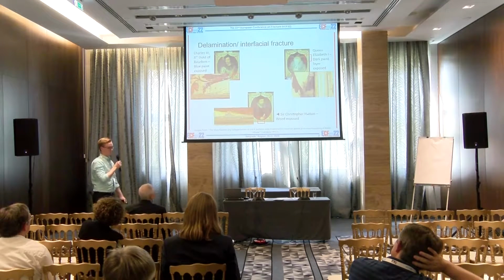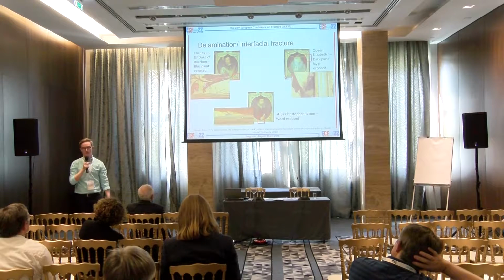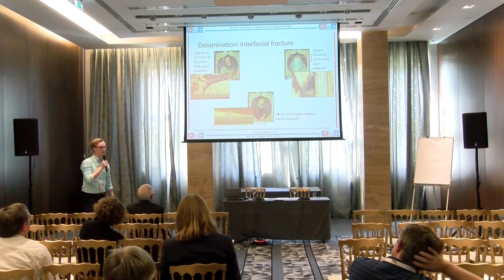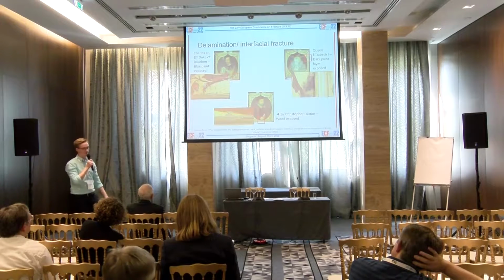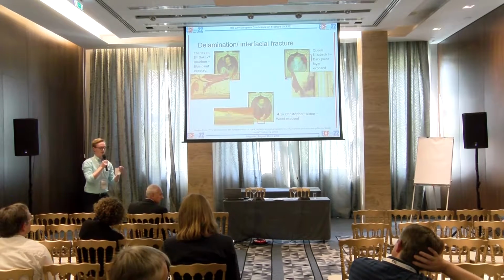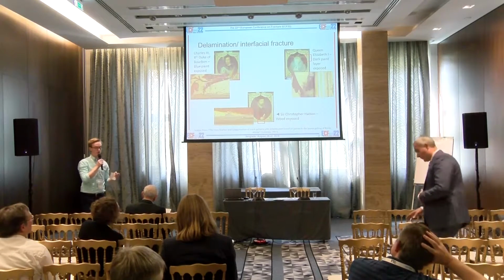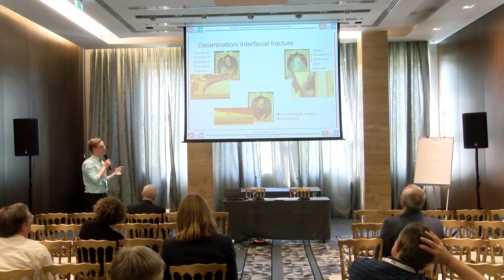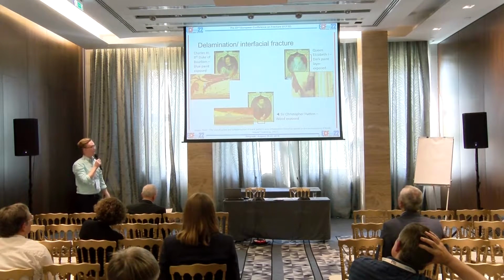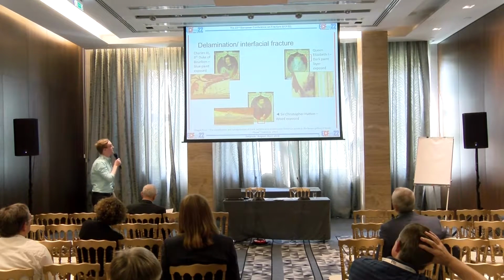So, paintings are complex, multi-layered structures, and due to the hygroscopic nature of the layers, strains are set up in the paintings, and due to the different dimensional response due to humidity cycles, strain differentials are induced between the layers, and this causes shear stresses along the interfaces and then leads to a delamination in the painting.